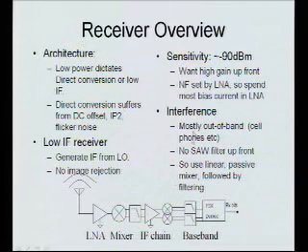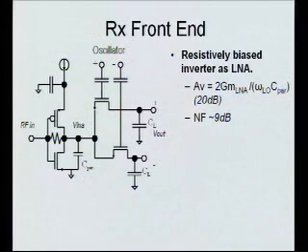The other thing that's noteworthy is since we're in the ISM band, the ISM band is mostly filled with relatively weak signals. It's a completely unlicensed band, so they're not really allowed to blast power there. So most of our interference is out of band, cell phones and things. On the other hand, we have no SAW filter up front, because those are expensive, and that'll be our whole buck by itself. So we're going to have to handle whatever wideband stuff is out there. So we need to be pretty linear, and I'll show you some neat tricks using passive mixers that allow you to be very linear.